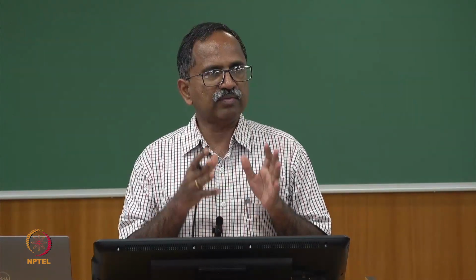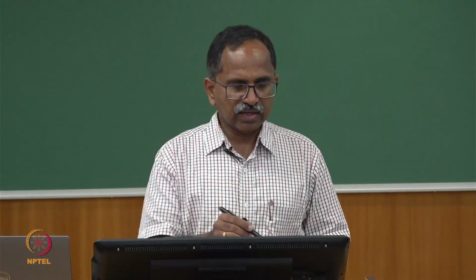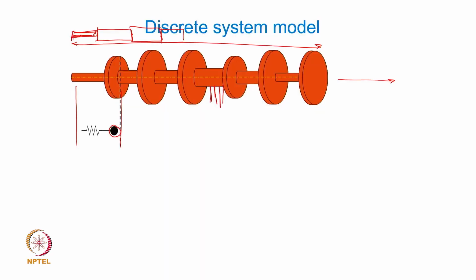You treat each segment separately, and the vibration will happen only if you have a mass and a stiffness. That means there has to be an element for storing strain energy and an element for the kinetic energy. So what we do is, each segment will have a lumped inertia element and an element to store the strain energy. So you have a stiffness and a mass or inertia element, and together they constitute a segment. And when you couple all such segments one after the other, you get the original system. That's the philosophy here.